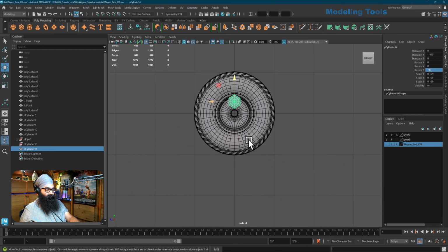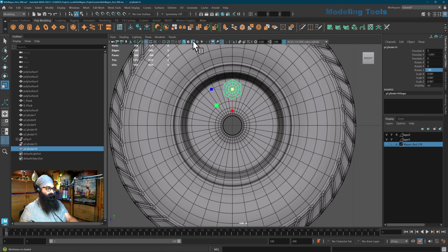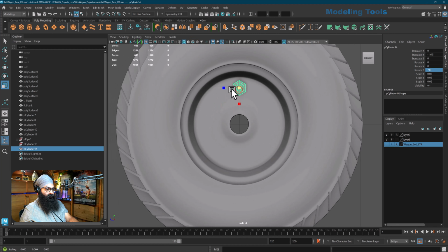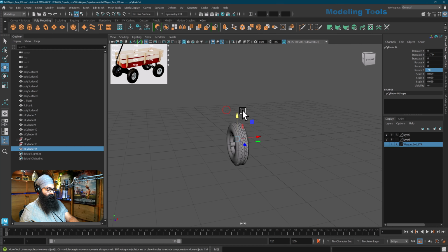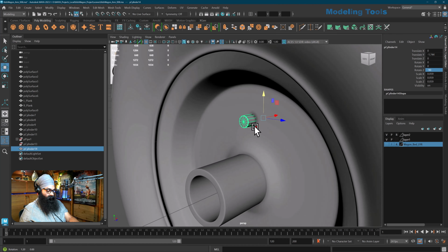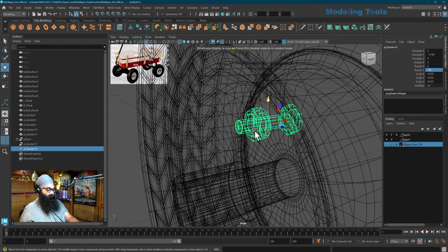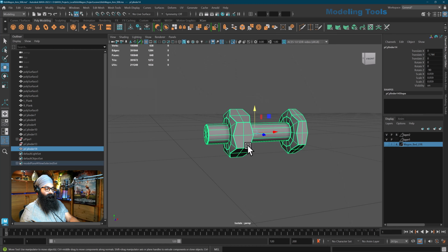I'm going to go to the right side this time and keep scaling it till you get this one to the right size. So I'm going to turn off this wireframe. So just leave that one on. And something around here is good size. Now let's look at the inside portion and look like that nut that we created is not coming all the way out. So although we have combined it, we haven't merged it together. There's a difference between merge and combining, which we are going to be looking at a little bit later.